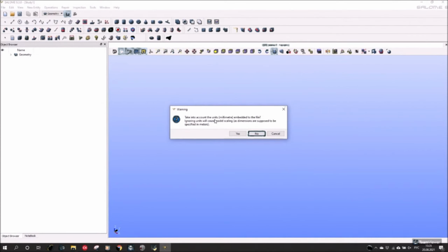And here is a question about the partition operation. This operation is to find contact surfaces between casting and mold and other parts of the casting. So I will press yes, and geometry input completed successfully. If I want to rotate the geometry, I will use the left mouse button. To scale, I will roll the wheel, and the middle button is to drag the geometry.